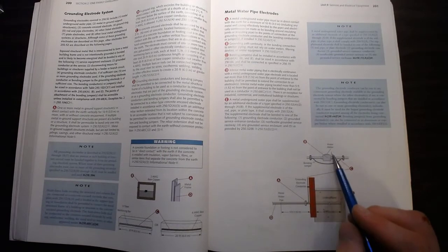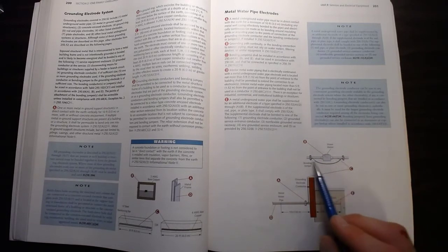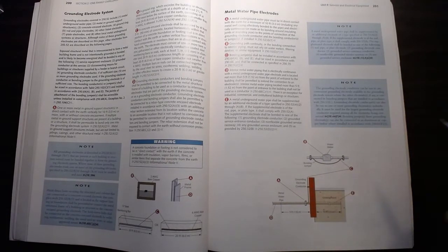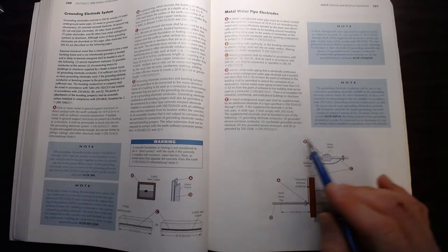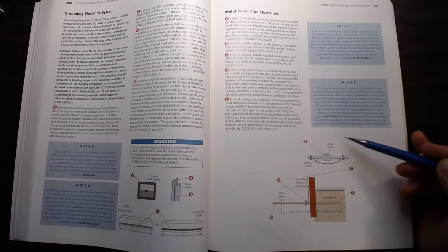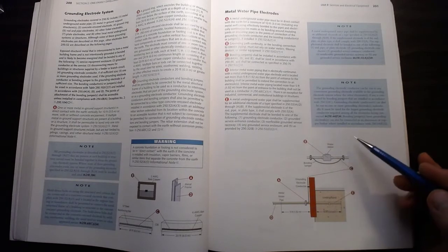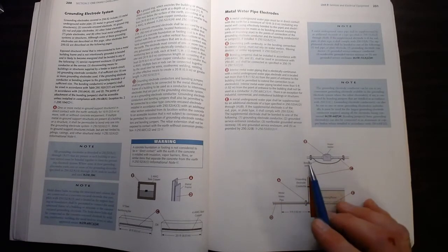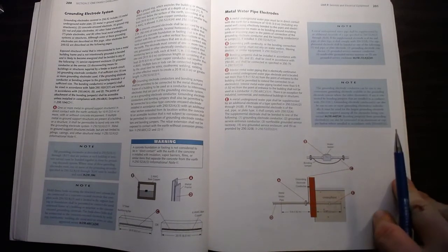The other reason for this is when the water company comes out and they need to remove and work on that water meter, they don't want to pull an arc because current is now traveling across this pipe because it's connected to other services that have neutral current on them. So there can be a balancing current of 1 to 2 amps going across the water system when you're looking at the aggregate of current flow from house to house. So when they open this up, they don't want to get current across there. Or if the utility has an open neutral connection somewhere, then one of these services is going to carry more current. So this bypass jumper is necessary.